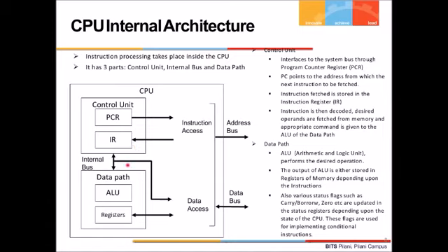So in this data unit, there is the ALU. Basically the data path is related to processing of data. So where does data processing happen? Obviously, if you issue some instruction, say add some register to another register, what happens? You need registers, and those register contents finally go to the arithmetic logic unit, and the operation happens there, right? So the ALU performs the desired operation, and the output of the ALU is either stored in a register or memory. That's why the data path should have the registers. Okay, and the various status flags.